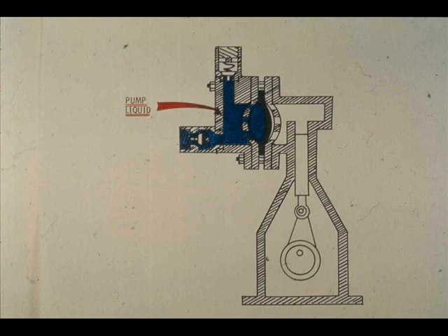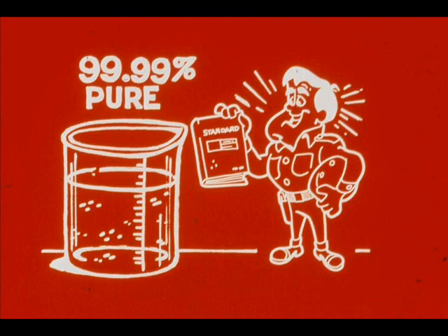Note that the liquid being pumped does not touch any part of the pump that requires lubricating oil. Some liquids must be kept so pure that they cannot stand even minute contamination from traces of lubricating oil. A diaphragm pump is a good choice for pumping such liquids.